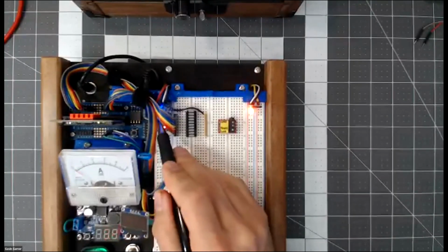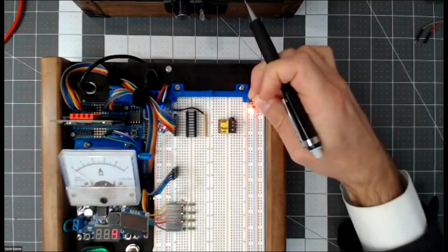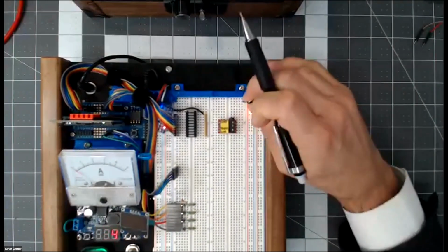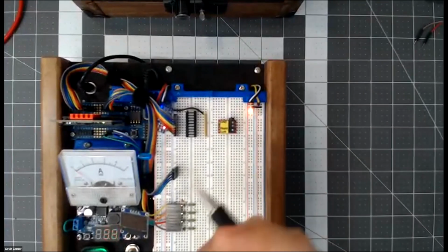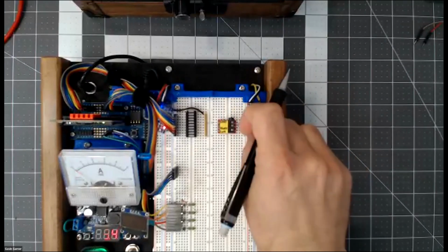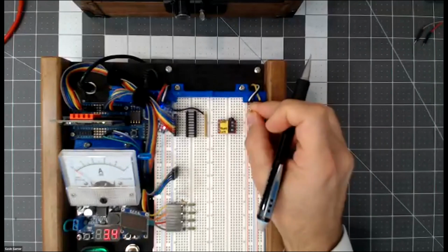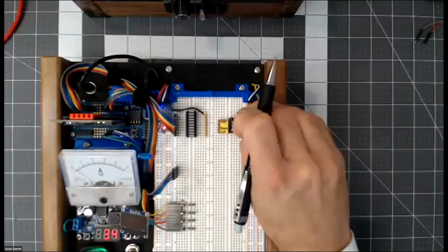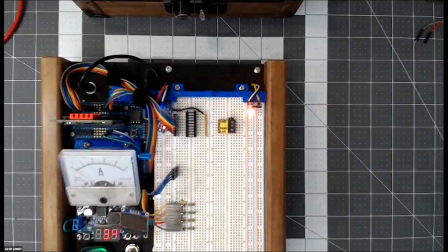And I've also put little LEDs in here to show them if they blow up their power supply. So if they lose, say, their 3.3 volt supply, then this will go off and they'll know. These are kind of cool. They're LEDs with little resistors built inside of the LEDs. They're optimized for 12 volts, but it's kind of neat to not have to use current limiting resistors with the LEDs. But I've decided that would get too confusing to use throughout the course, because people would take the course and then go out and get any old LED and just blow it up instantly by not putting a current limiting resistor in it.